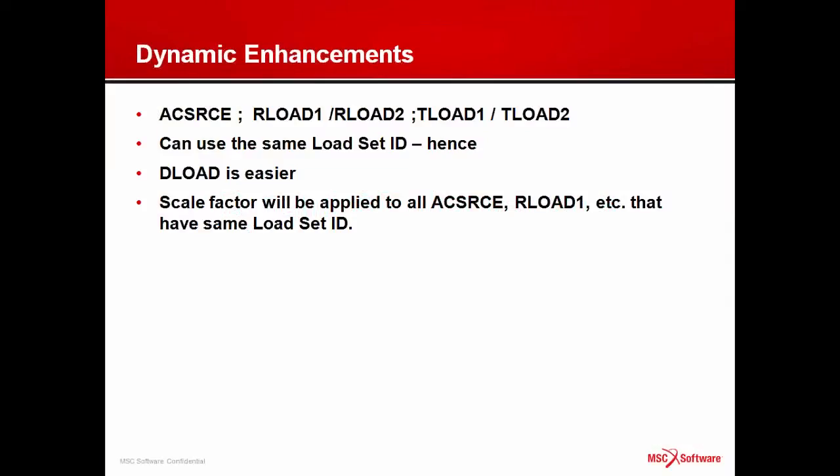Other dynamic enhancements is an ease of use. When you had a large number of RLOAD1s, RLOAD2s, TLOAD1s, TLOAD2s, you gave each one of them a different load set ID, and then the DLOAD option was very long because you had to mention each one of these load set IDs.